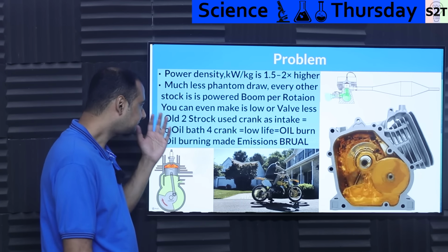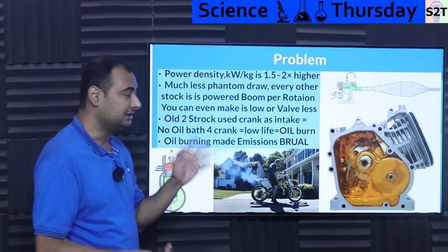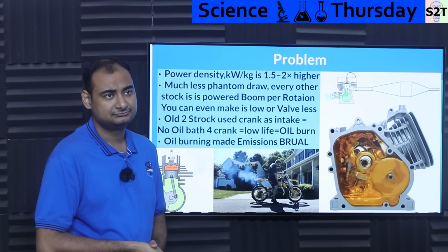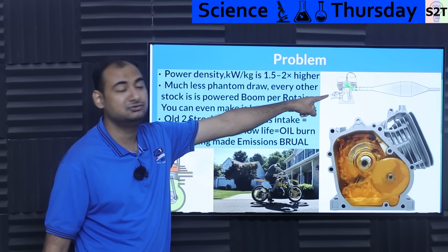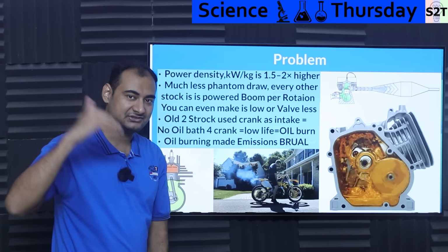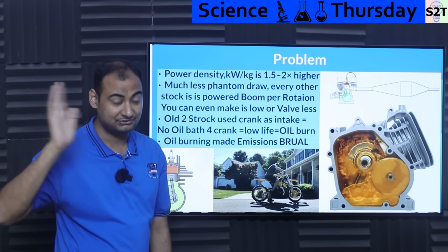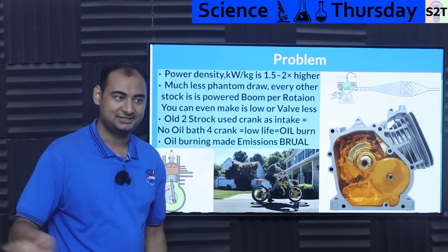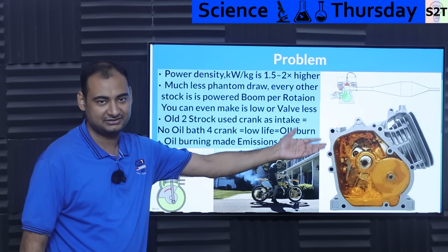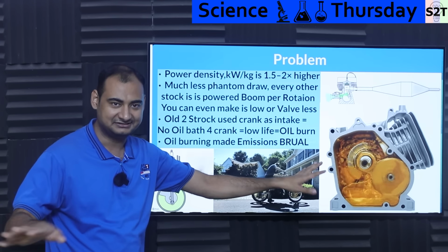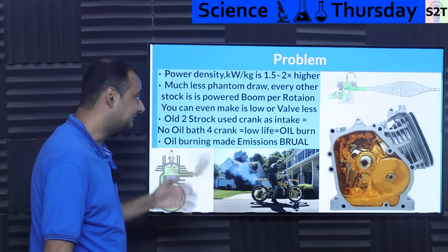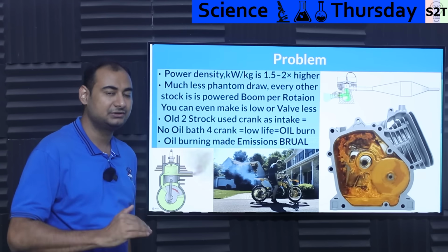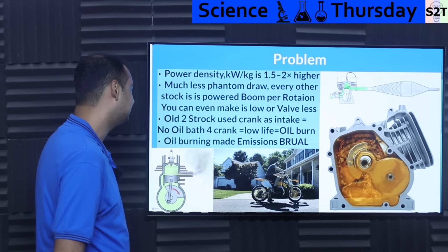So fundamentally, you can design a two-stroke system in such a way that it has no valve or only one valve. Some designs can have zero valves, and yes, I do mean even without a reed valve. There are certain piston window designs that allow you to remove the reed valve also. So if you want to design it, you can have a system that has just one moving part, like piston, crank and all that jazz, and there is nothing more than that. That's why, if you want to, you can make it ludicrously power dense. Even today, you can make these puppies ludicrously power dense.